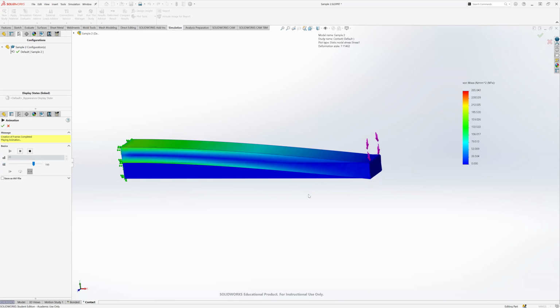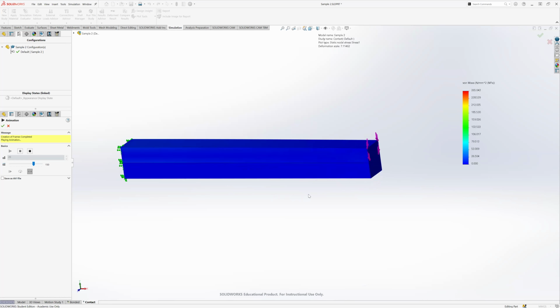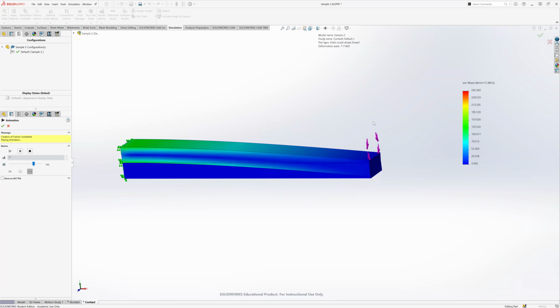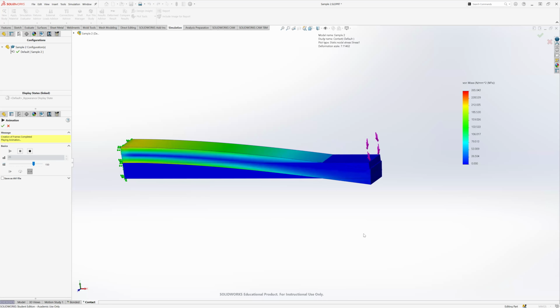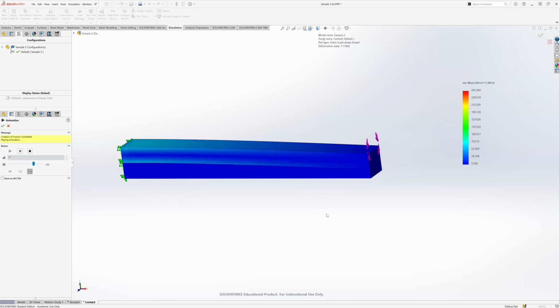Contact condition is also, they actually changed this, I think. I forget which year of SolidWorks. It was rather recent when they changed it. A contact condition was also what was previously known as non-penetration or no penetration, meaning that one body, one part, one whatever cannot penetrate another. So sometimes you'll hear people call it non-penetration.